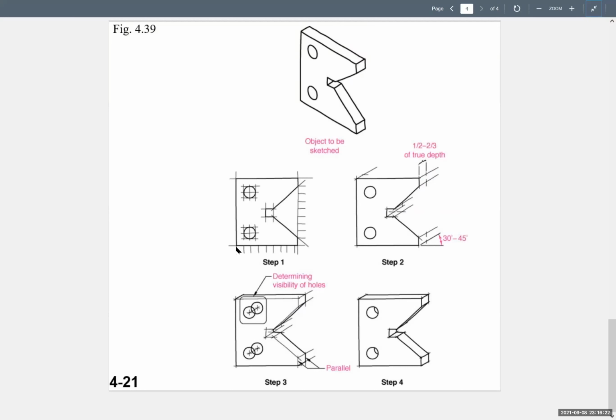So I draw a box that has the total width and the total height, and then I know what this height is here and what this height is here, and I know how far it's going back in width, and I'm basically cutting out, it's kind of like cutting out the front face from this front box. And then I also know what the diameter is of the two circles, and I know where the center of each circle is, so I'm able to draw them as well. And then I'm erasing my construction lines, and now I have my front face of what it looks like.